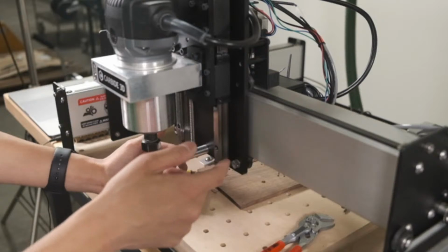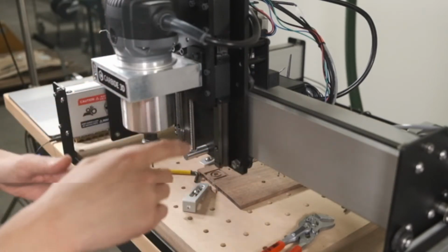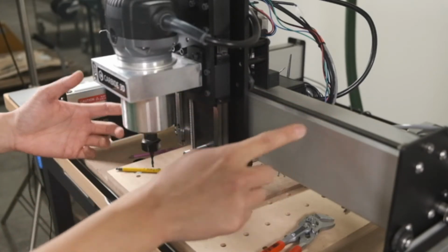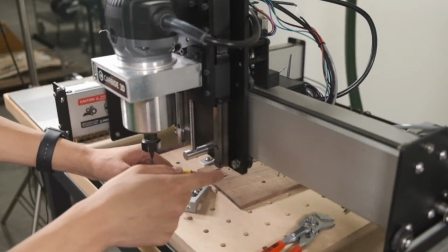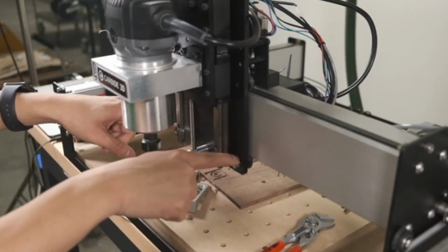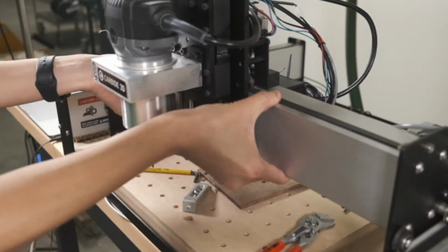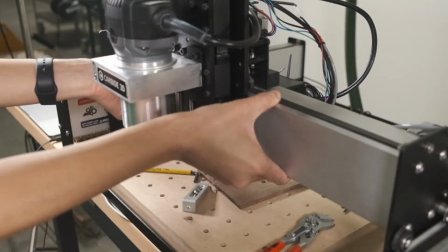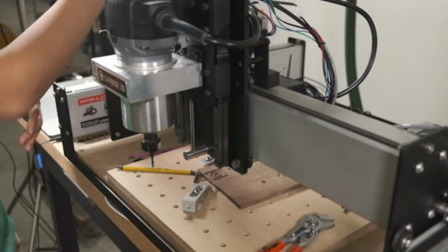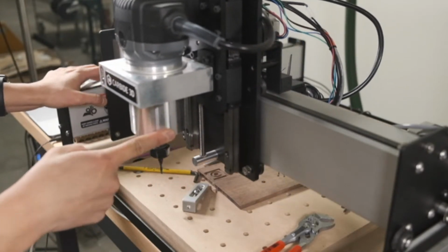So if you turn off the machine and you push the carriage back and forth, you might feel little bumps periodically, like every 1.5 inches or so. That tells you that there's a periodic error, and it's likely linked to your V-wheels. And also, if you have the V-wheels really snug down on this rail, it's actually going to cause some friction. So normally, let me turn off the machine, this should roll pretty freely. Like, I shouldn't have to work very hard to move it.